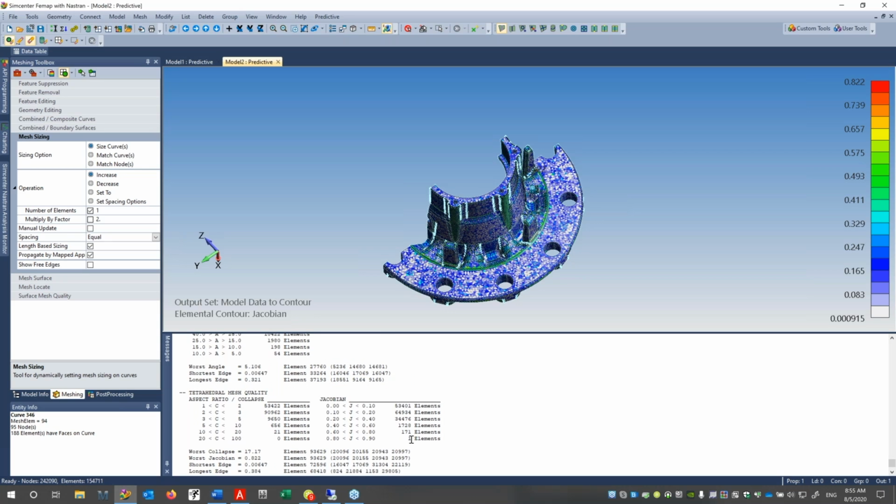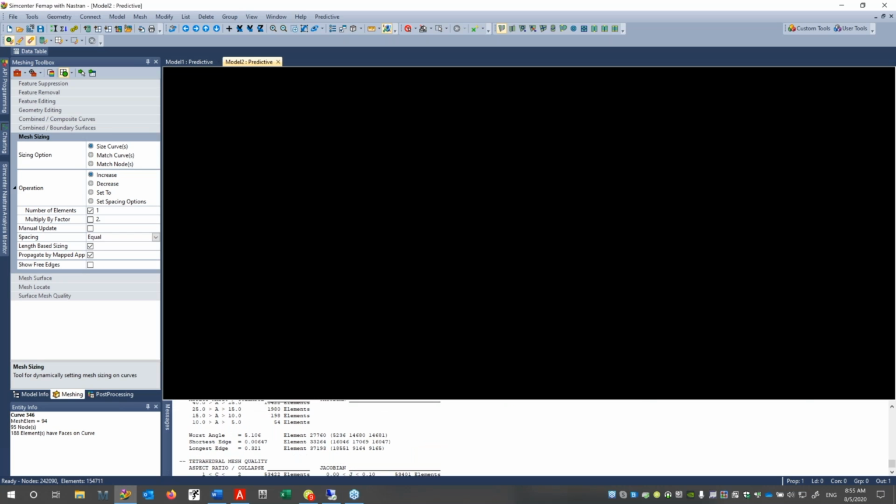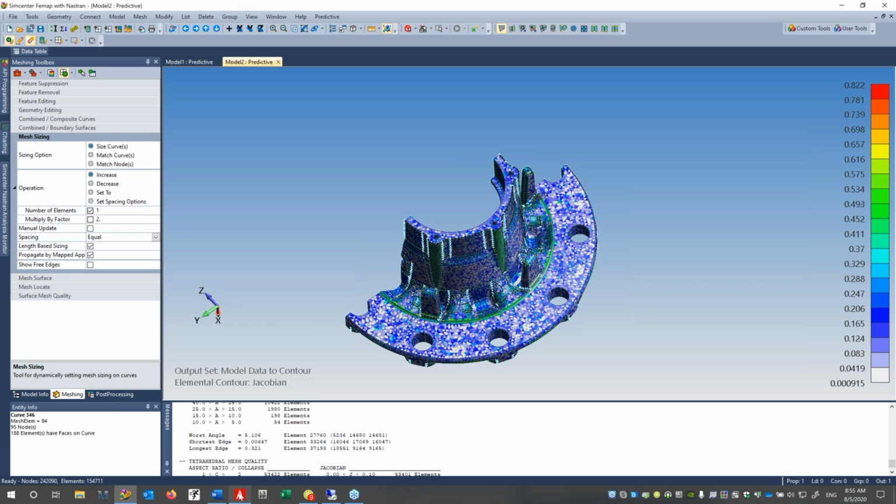That is a good mesh. Now, of course, it's one of those engineering things. If the distorted elements are in a low stress region, it doesn't matter because there's low gradient, and so it's good to go. If it's high stresses, you want good elements, of course. But that takes care of this. So where am I? 855. Not bad. Okay.